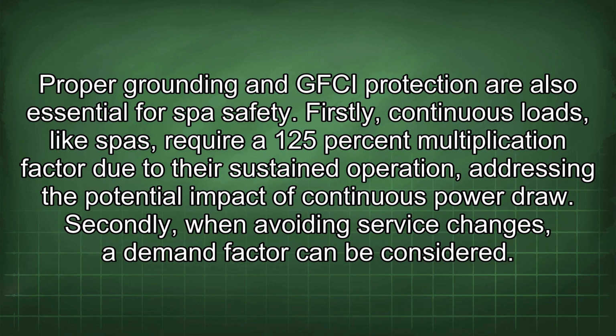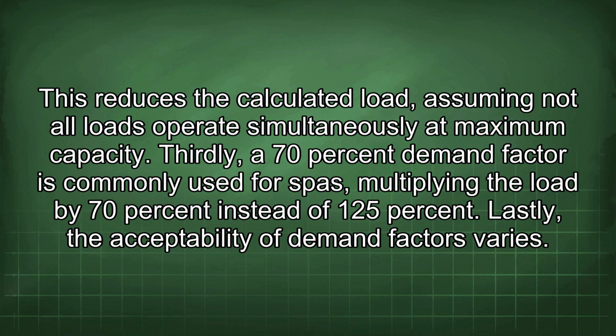Firstly, continuous loads, like SPAs, require a 125% multiplication factor due to the sustained operation, addressing the potential impact of continuous power draw. Secondly, when avoiding service changes, a demand factor can be considered. This reduces the calculated load, assuming not all loads operate simultaneously at maximum capacity.